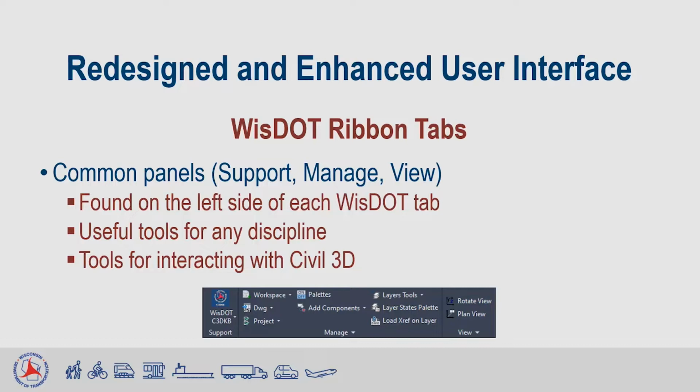The Manage panel is really all about managing your project and drawings. The View panel is just really about navigating your model. It gives you a quick way to rotate your view without changing your UCS. There's a button there to return you back to a regular plan view.